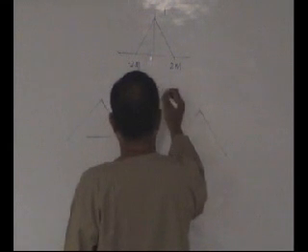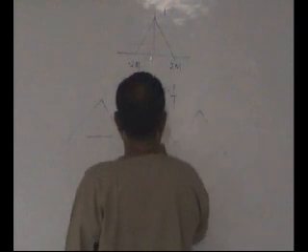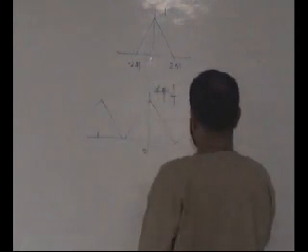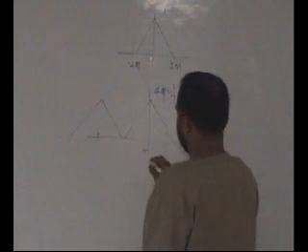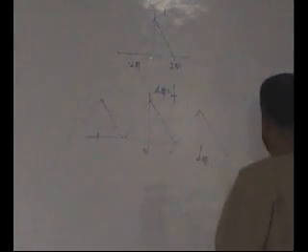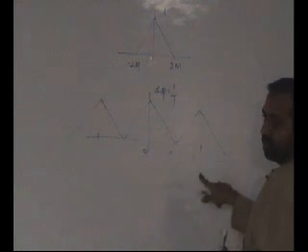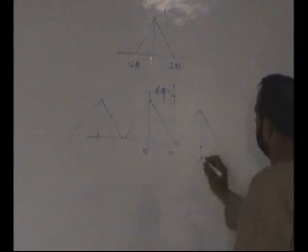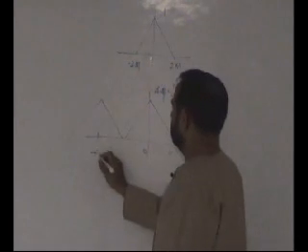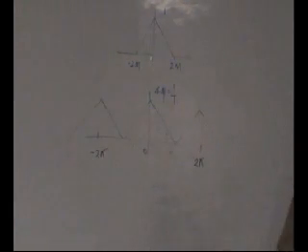It is 4 megahertz, so 4 mega, which is equal to 1 over T. And in the digital domain, what will be the frequency where you are making copies? 2 pi and minus 2 pi. This is the digital signal if sampled at 4 megahertz. What if the signal is sampled at 8 megahertz? This is what an interpolation is. If the signal is sampled at 8 megahertz, at least in the frequency domain, it will look like this.